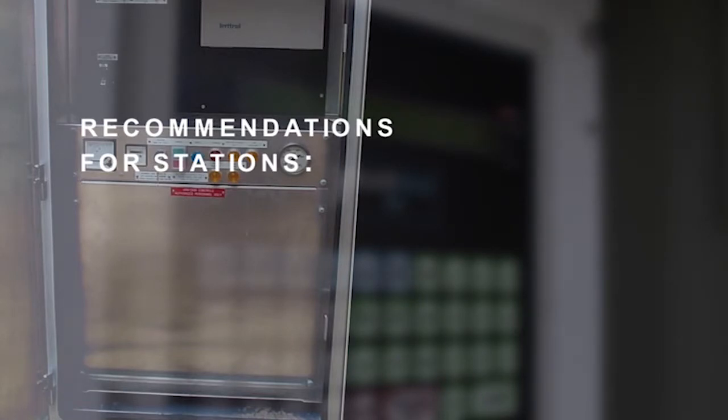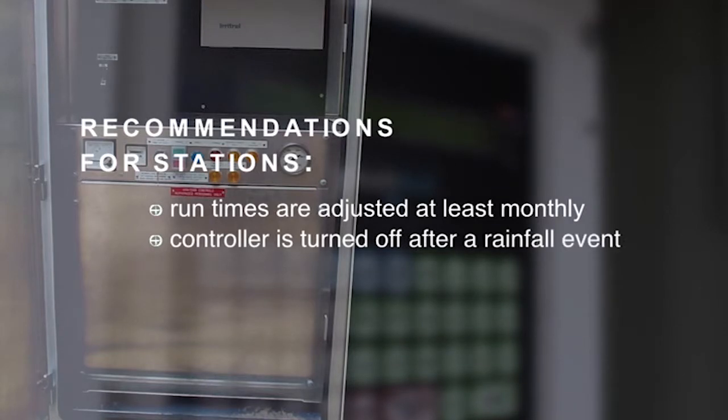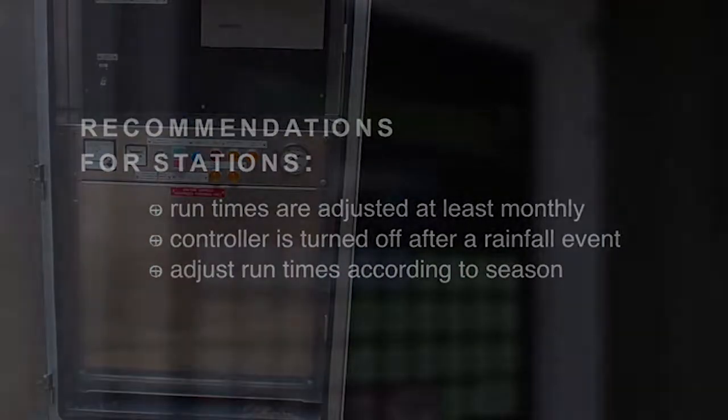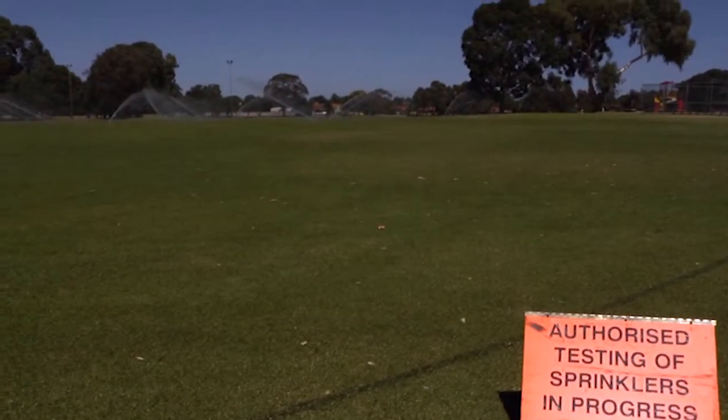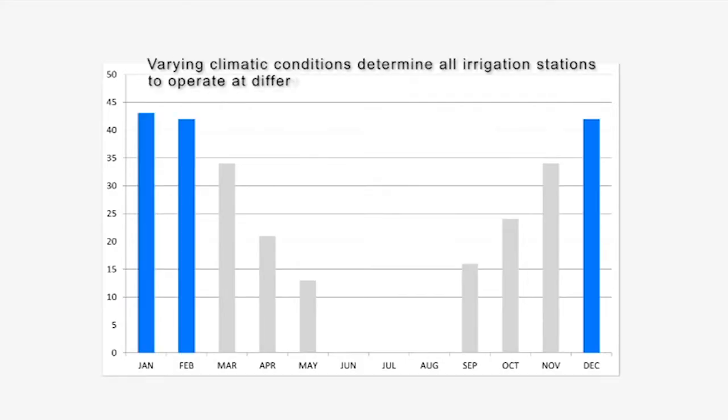It is recommended that the station run times are adjusted at least monthly and that the controller is turned off after a rainfall event. Summer months are when the irrigation demand is highest, and demand drops off during spring and autumn, so runtime should be adjusted accordingly. Australia has a wide variety of climatic conditions, and in some areas the irrigation system can be and should be turned off during winter. In Western Australia and some other states, local water regulations demand that sprinklers are turned off during winter.